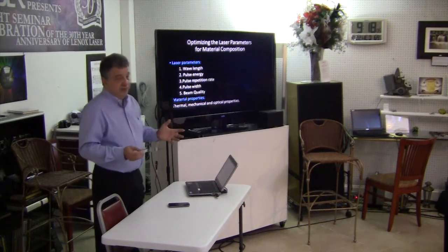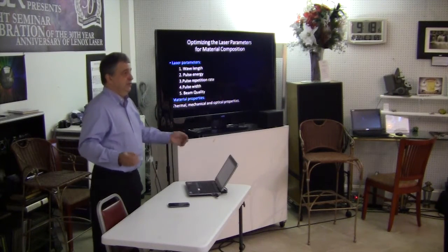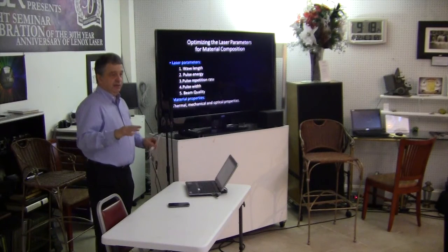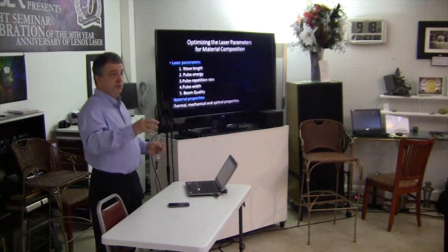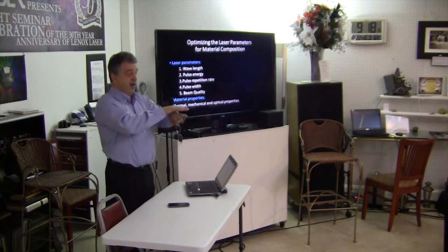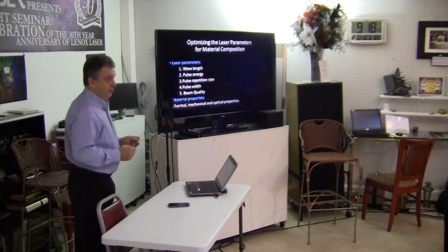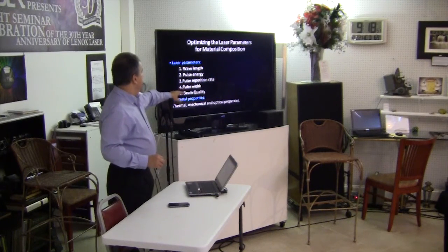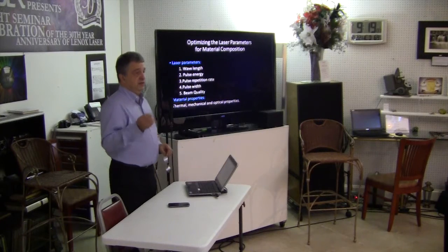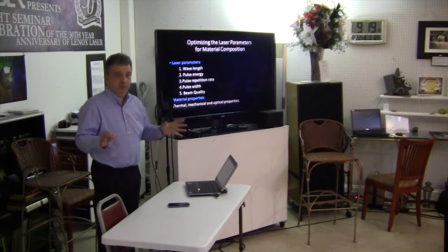The pulse energy, of course, you can have a huge energy in the pulse, but the material cannot take it all. Everybody in this world is trying to resist anything that comes extra to him. So if it's too much, it will be pretty much rejected by the material. For example, if you're shooting a piece of metal with the laser beam, all of a sudden the plasma, the electrons are being extracted. They go up, and it's the so-called screening effect. And that electron cloud screens your sample from the rest of the pulse that's coming in. So as much as you want to throw in, you can't. And there are pulse repetition rate and pulse widths, but the most important parameter is also beam quality. And this is where the new upcoming lasers and improvement in the laser technology, bringing the beam quality to theoretically diffraction limited beams, is taking place.